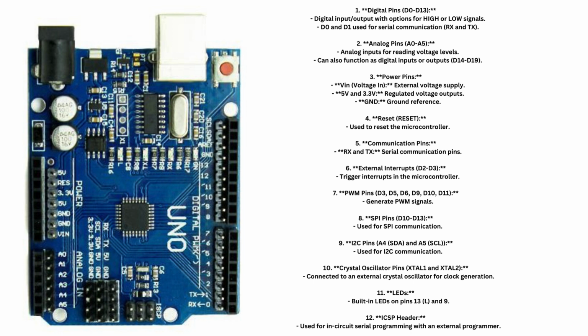GND, ground reference. 4. Reset, used to reset the microcontroller. 5. Communication pins, RX and TX, serial communication pins. 6. External interrupts, D2 and D3, trigger interrupts in the microcontroller.